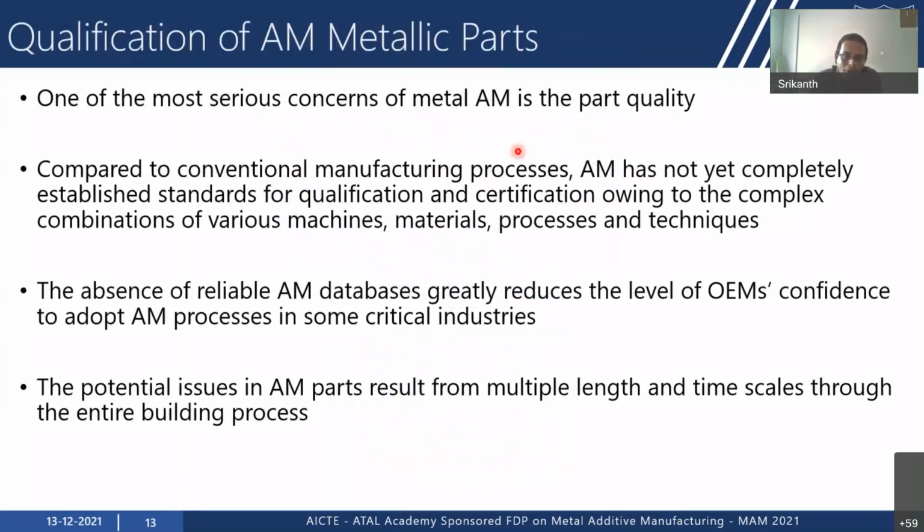So one of the important concerns in metal additive manufacturing is that of part quality. Now, when you compare metal additive manufacturing or laser additive manufacturing techniques to standard conventional manufacturing processes, one thing becomes obvious: AM has not yet completely established standards for qualification and certification of the AM process.